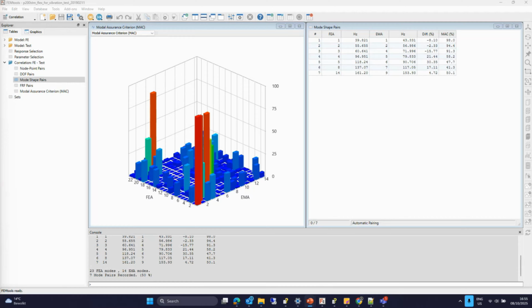Okay. The maximum order selection is default, if you saw the MPE plot, so the question is how to determine what the maximum order should be in the modal extraction. The estimation that FEMtools provides is based on a peak counting algorithm. So we estimate how many peaks there are in the frequency range of interest.